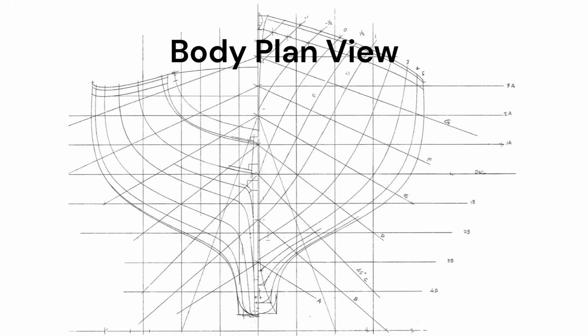The diagonals are a little more difficult. They are usually not 45 degrees and not always inclined equal. How they are defined depends on the designer. In the picture you can see that the diagonals have different angles as well. Usually, they are defined on the drawing with notes stating the location or are drawn to a measured distance. The table of offsets states the distance from the vertical line along the diagonal.